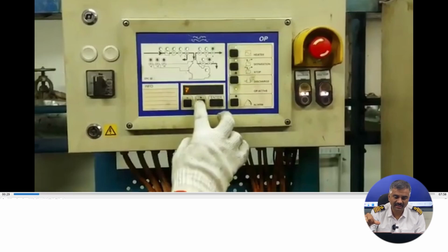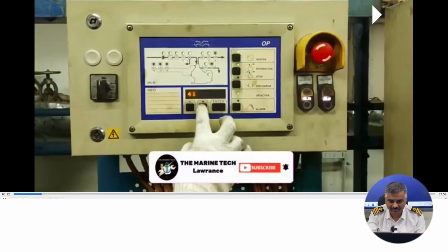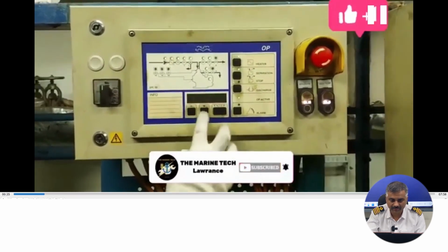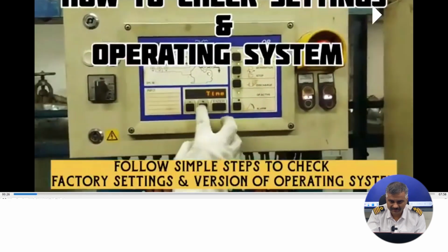You press enter, then enter the process parameters PR12, then press plus and enter, and go to the end of the process parameters: 19, 20, 21, 40, end of the process parameters, then IO. Then you press plus and enter together to get into the installation parameters, then you again go plus, and then you come to factory. You can see this.